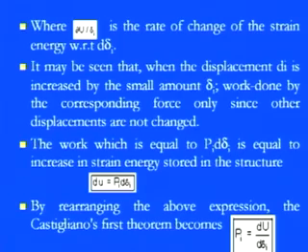And by simply rearranging those things, we can say that using Castigliano's theorem, the external point load can be easily calculated if we know the increment in strain energy within the domain of the change in displacement. Whatever small amount of displacement change or increment there is in that domain, whatever strain energy comes, it will simply locate this force application.